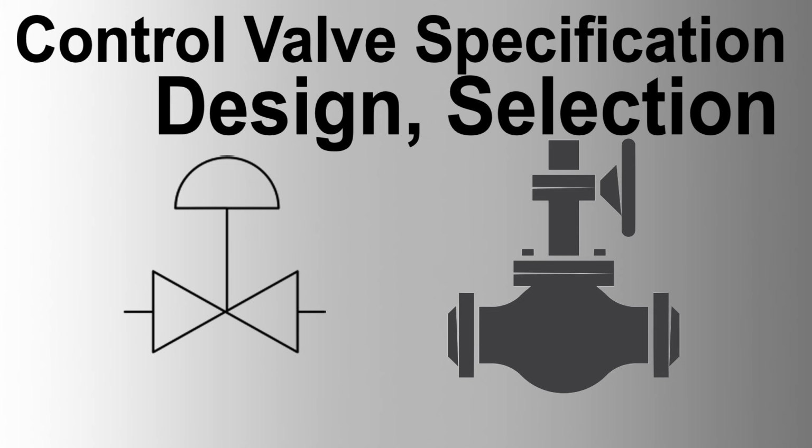3.2 Valve body selection. Types: globe, cage type, rotary, eccentric plug or segmented ball, butterfly, single or double seat globe, ball. Materials: suitable for H2S service, complying with NACE MR0175. Sizes: standard sizes from 1 inch to 12 inch, unless specified otherwise. Flanges: ASME class rating as per piping class, minimum 150 pounds.